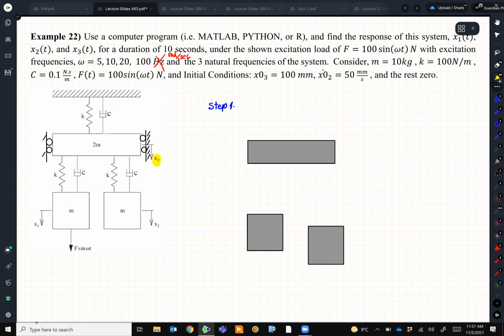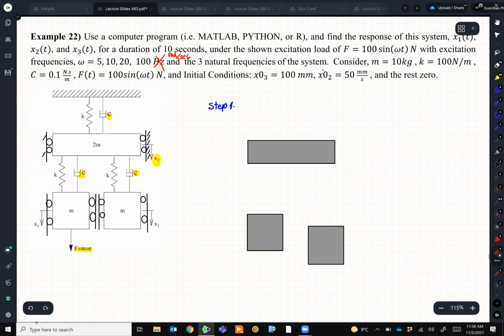And the same with m. With the two other masses, just for simplicity, we show them like that, but we assume that they are inside the rail and they can only move up and down without moving to the left or right. So like before, you disturb them, right? And remember, you have also an external force and you have damping. So this is the most complete case for an n degree of freedom system, which is a 3DOF system here.